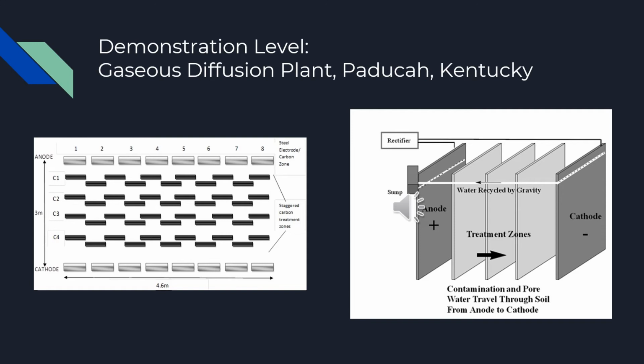The level of contamination fell to 1.2 parts per million. The TCE concentration in the carbon treatment zones were high and were replaced. The cost for the complete remediation in this test was 1,310 per cubic yard. The electroosmosis flushes TCE from clay since this clay did not absorb much TCE and allowed the contaminant to move